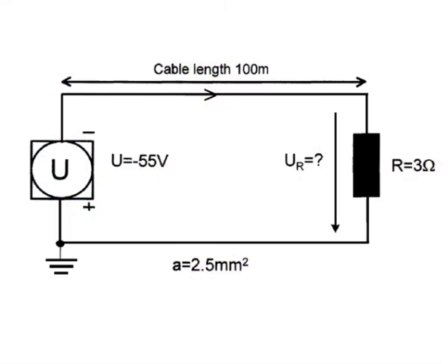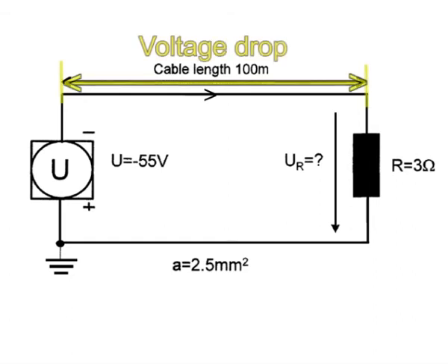As we already mentioned, all cables have cable resistance. The longer the cable, the higher the resistance will be. This will cause a proportionately higher voltage drop. Now, voltage drop is a more important factor at high currents.